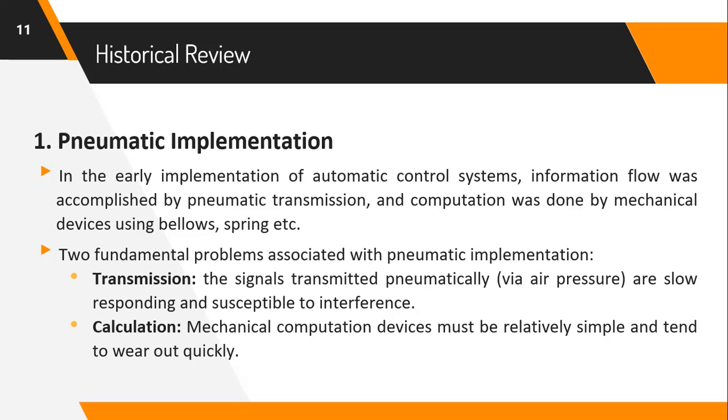There are two fundamental problems associated with the pneumatic implementation. First, in the transmission, the signals transmitted pneumatically are slow responding and susceptible to interference. And in calculation, the mechanical computation devices must be relatively simple and tend to wear out quickly.